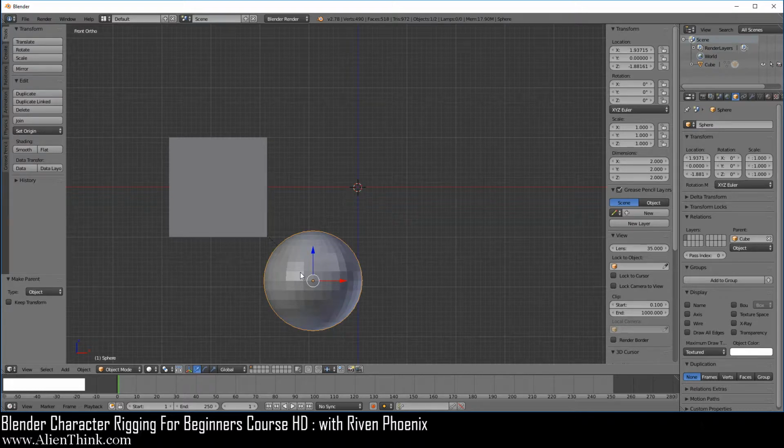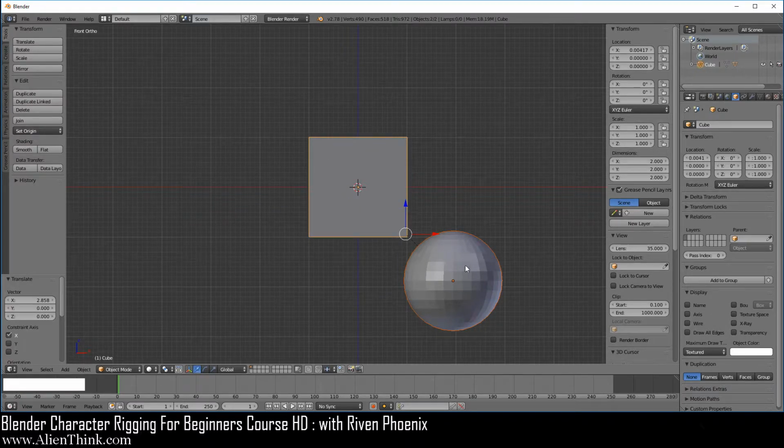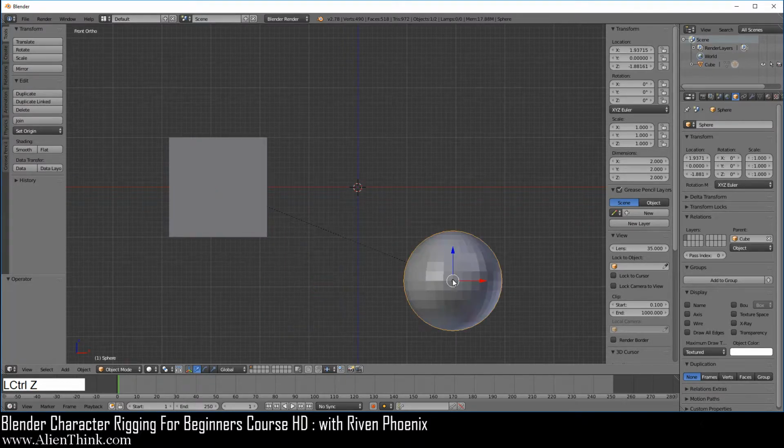So this is why it's moving, meaning that if we click on this child, press the Shift key down and now click on this cube, basically if we take this cube's origin point and put it to the center over here, you'll notice that it's moving the child exactly where it started out from, right? So if we do Control Z to undo all this, you'll notice that the child goes back to where it was. This is what this is doing over here. Okay, so when you select this, this is why this thing moved. Go ahead and X this out.